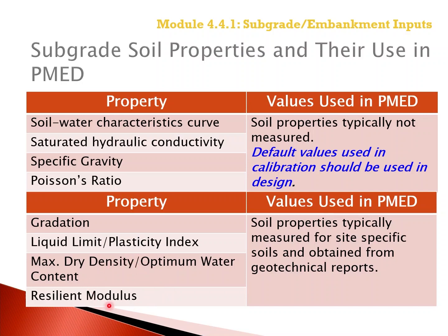So these should definitely be compatible, entering the resilient modulus that's consistent with how it was determined from test specimens in terms of dry density and the water content.